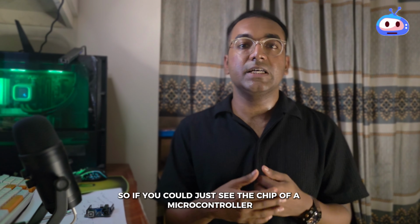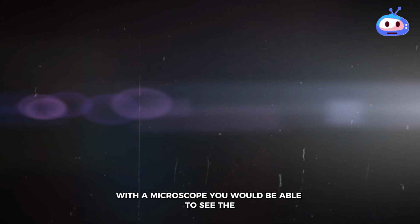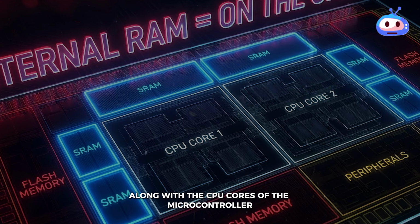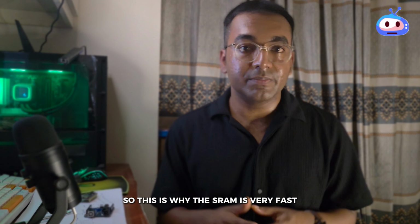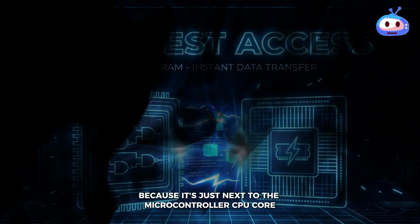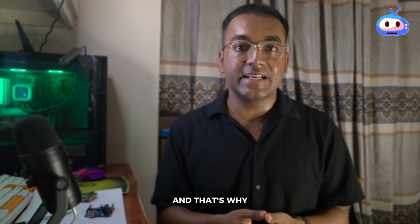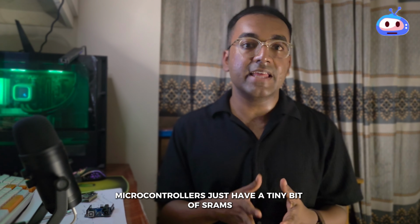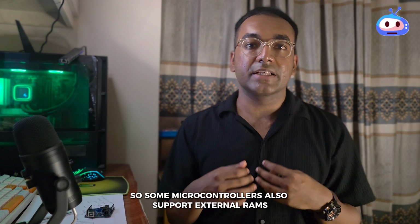If you could see the chip of a microcontroller with a microscope, you would be able to see the SRAM along with the CPU cores of the microcontroller. This is why the SRAM is very fast, because it's right next to the CPU core. But it's expensive to make, and that's why microcontrollers have only a tiny bit of SRAM. Some microcontrollers also support external RAM.